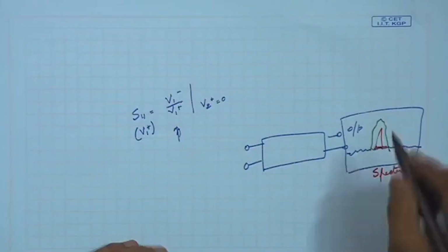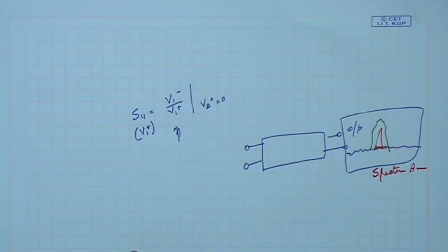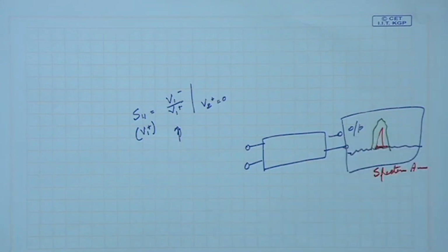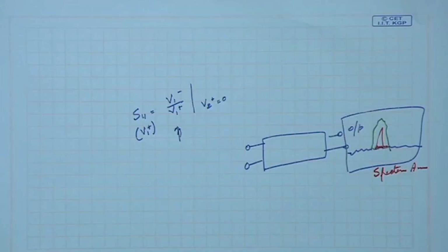Typically, it depends on what you prefer. You may call this a signal, I may say no, unless and until it becomes like this green one I will not say so. The green one means his definition of signal requires a somewhat higher dB than the red one's, but whatever you decide, okay, this is a signal, that means above the noise floor you have something. So the lower range of the dynamic range is fixed by the noise floor.